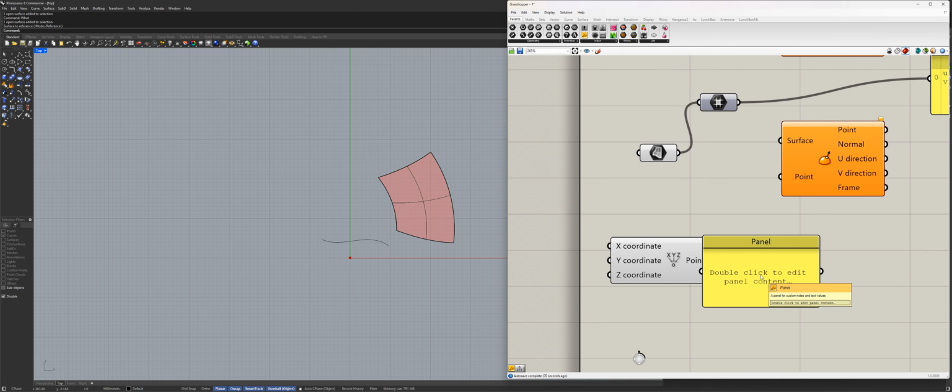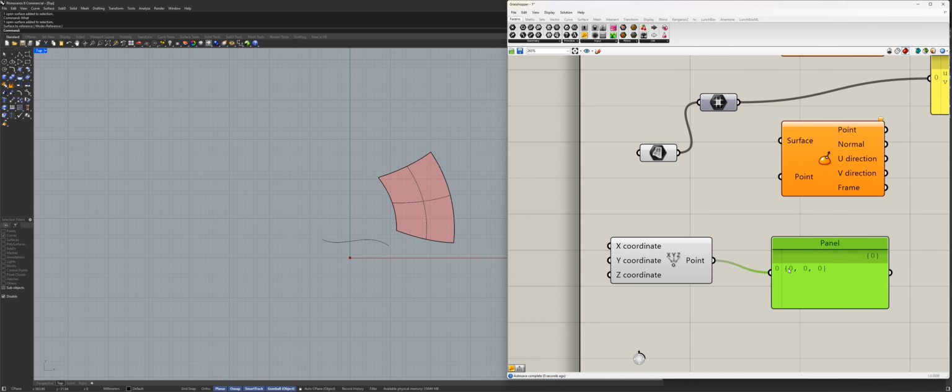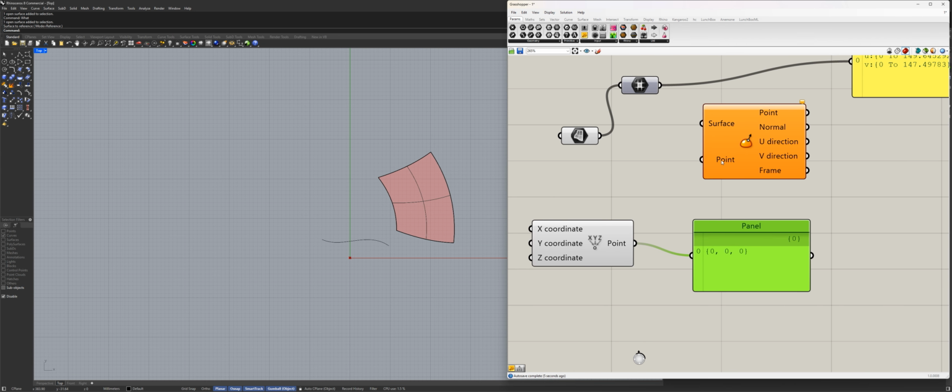So if we analyze this, it gives me the proper syntax, 0, 0, 0. The only problem is that the point here is 2 numbers, and this is 3 numbers. But a part of that syntax is correct. If it were only 0 with 0 with curly brackets, it would be exactly right. And Grasshopper is smart enough to know this. When you plug a point and it literally says, give me the point, it looks at this, it will automatically chop the third value here. It will get only 2.